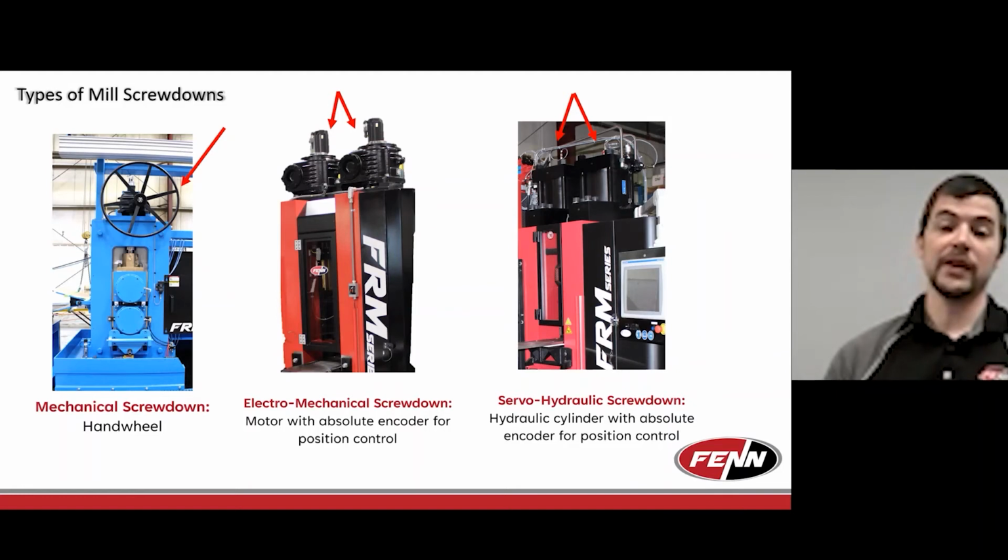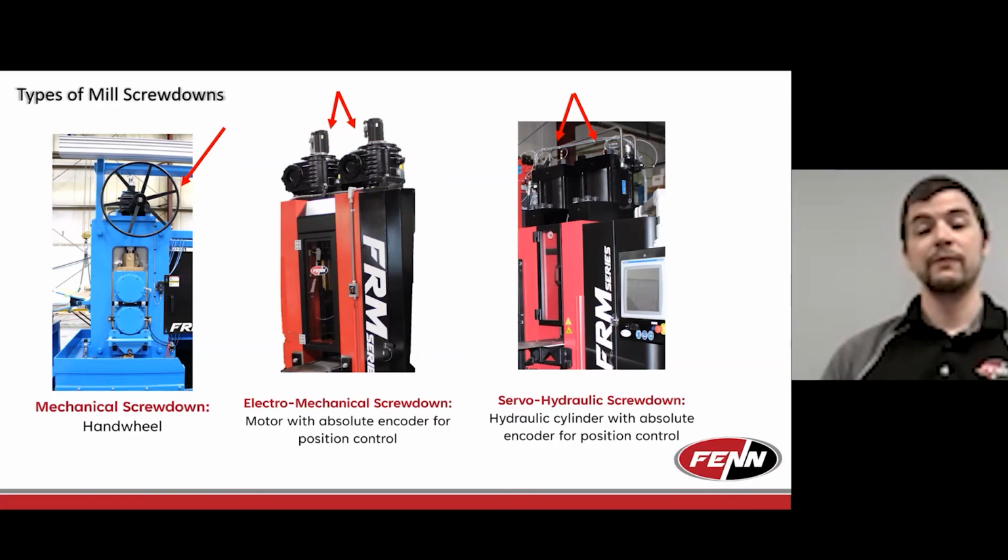When it comes to electromechanical versus servo hydraulics, the rule of thumb I state is that when designing a motor, any type of electromechanical screw down or a servo hydraulic, what you're looking for is either something that can move fast, something that can move precisely in terms of very tight, accurate motion, or something that can physically drive under load.